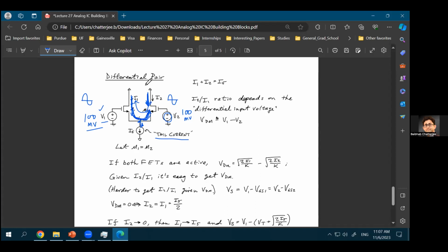So your output current will be 0 in that case. So how do you make sure that it can work as an amplifier? Provide the inputs as a differential version of each other. And we discussed this, that differential input does not only mean that you're taking a difference of the input. It means that if one input has a 0-degree phase, the other input will have a 180-degree phase. Okay, so this will have a 180-degree phase at the input itself.